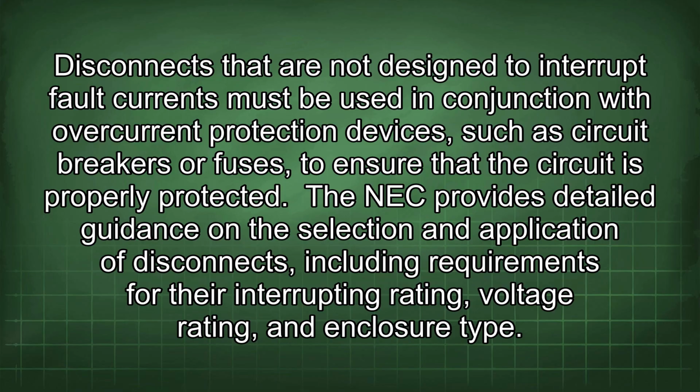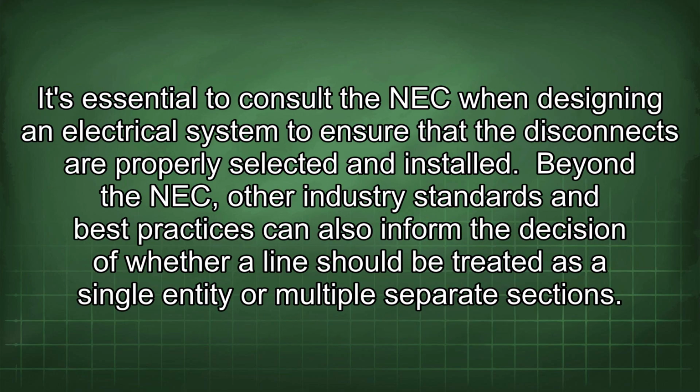The NEC provides detailed guidance on the selection and application of disconnects, including requirements for their interrupting rating, voltage rating, and enclosure type. It's essential to consult the NEC when designing an electrical system to ensure that the disconnects are properly selected and installed. Beyond the NEC, other industry standards and best practices can also inform the decision of whether a line should be treated as a single entity or multiple separate sections.